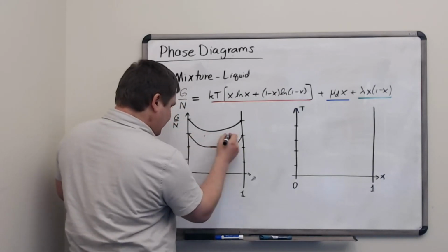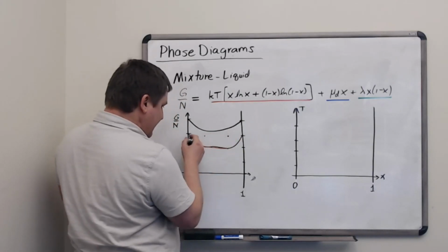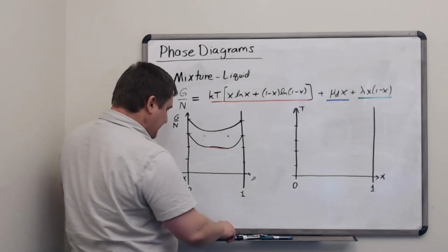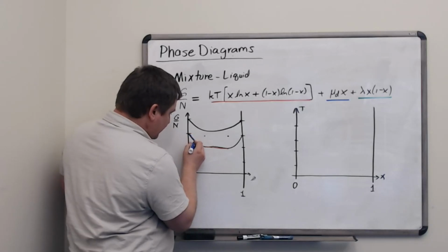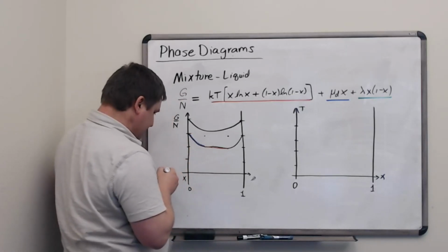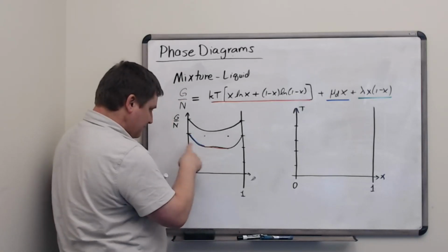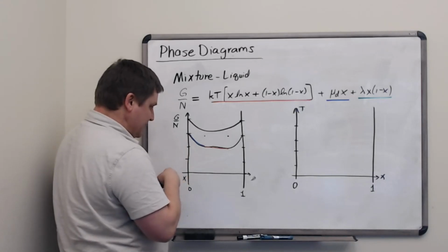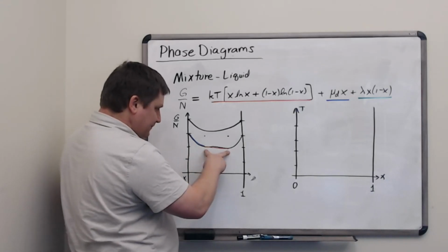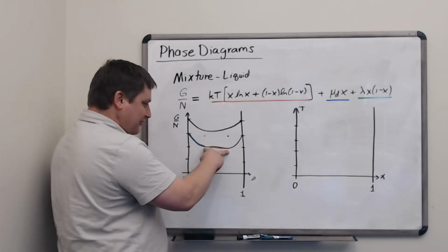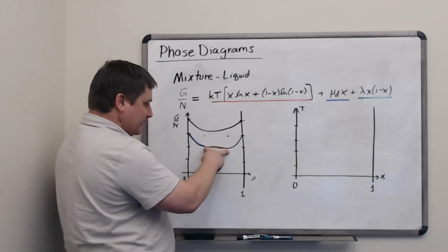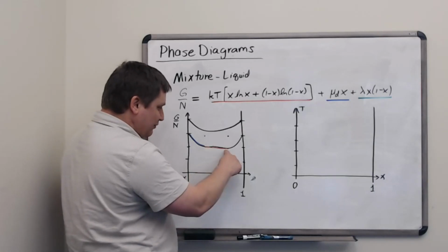At this temperature line, we've got a left side, which is representing a homogeneous mixture that has a lot fewer A molecules than B's. We've got a region in between here that is actually a convex hull region. It's a line joining 2 points.